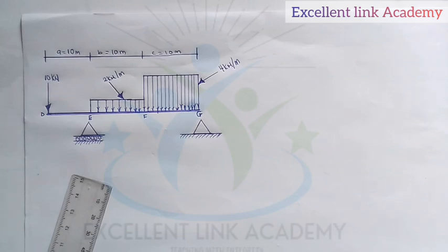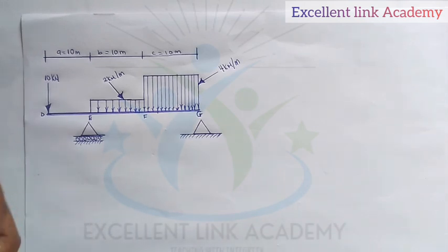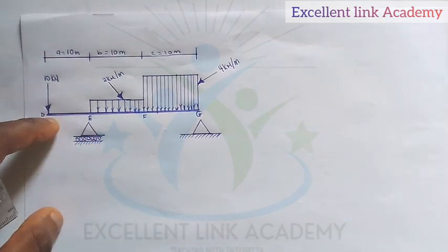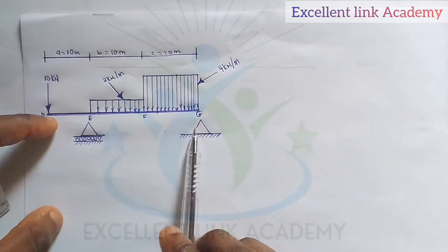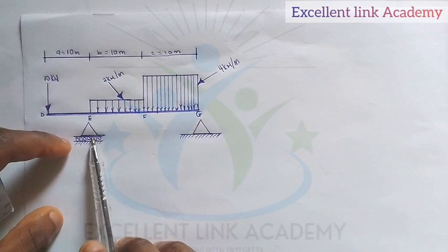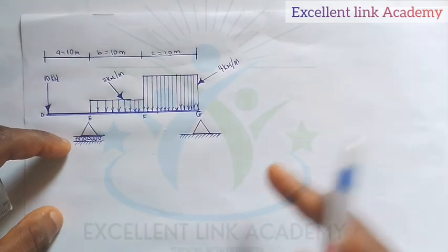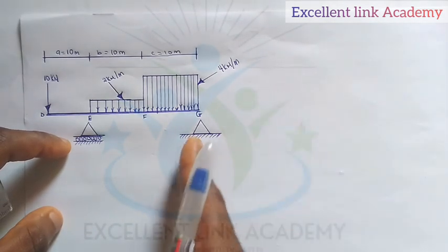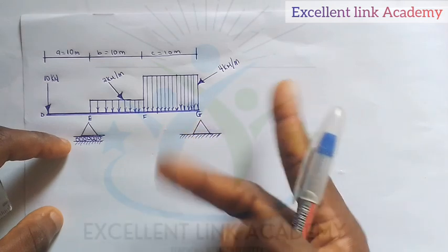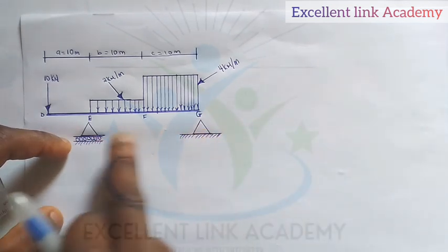We are told to do what? Determine the reaction at the support. Now, my first task here is I want you to note there are two things in this question that we need to be familiar with. Number one is the reaction. This is a roller support, and a roller support always has what? Only one reaction, which is what? The vertical reaction. But this is a pin support, or you call it a hinge support. It has only what? Two reactions, the vertical and what? Horizontal reaction. So note these two.